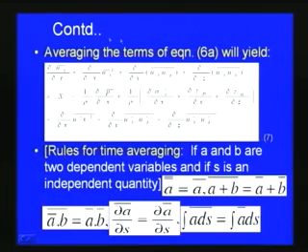So, if we use the time averaging concept, we can write, by averaging the terms, ∂ū_x/∂t + ∂/∂x(ū_x²) + ∂/∂y(ū_x ū_y) + ∂/∂z(ū_x ū_z) = X − (1/ρ)∂p̄/∂x + (1/ρ)[∂σ_x'/∂x + ∂τ_yx/∂y + ∂τ_zx/∂z] − ∂/∂x(u_x'²)‾ − ∂/∂y(u_x' u_y')‾ − ∂/∂z(u_x' u_z')‾.